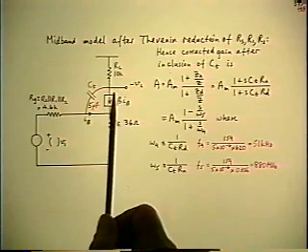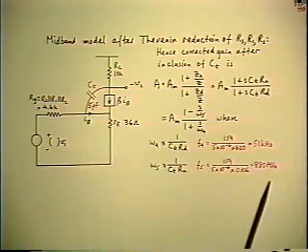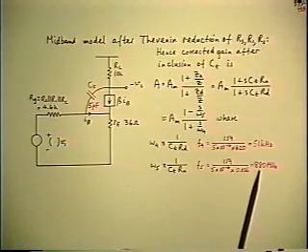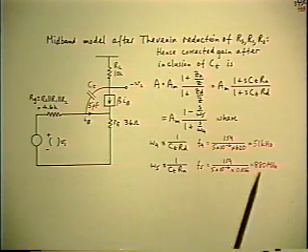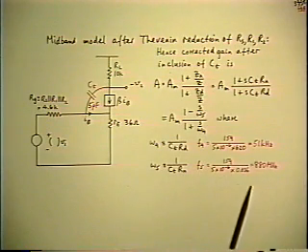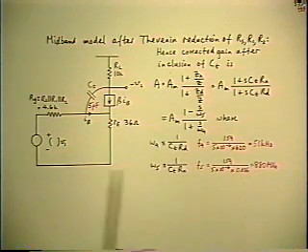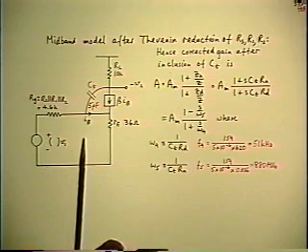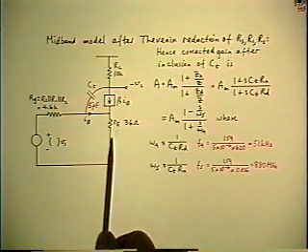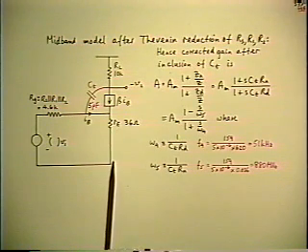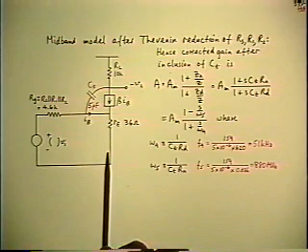Okay, so if the capacitor is 1,000 times bigger, this is now 880 kilohertz. Now it's down to a range where it may get in the way of some things you're looking at. Another reason may be, suppose you have an unbypassed emitter resistor down here, like the 2.2K we've had in the previous examples.